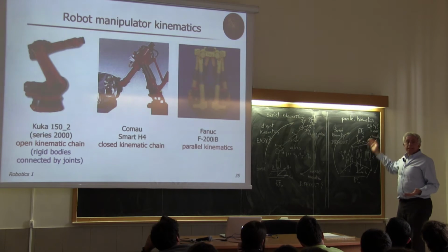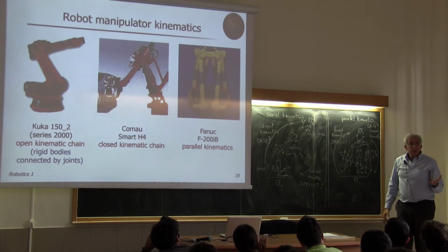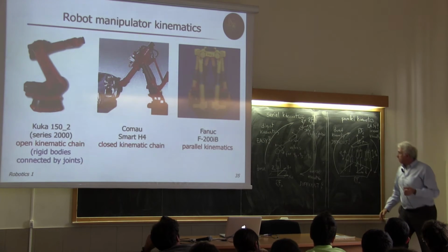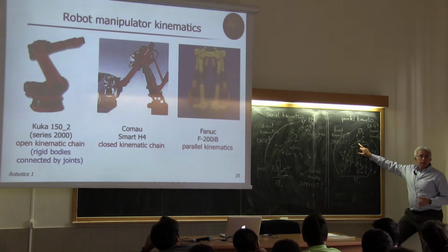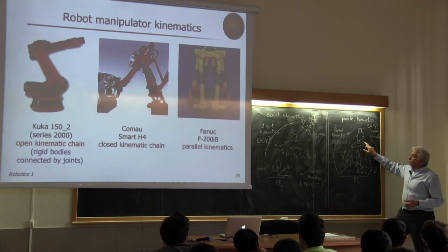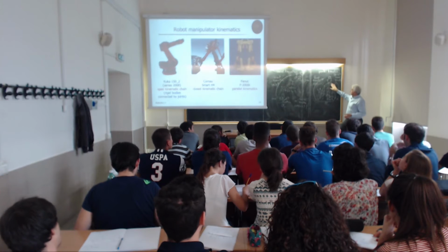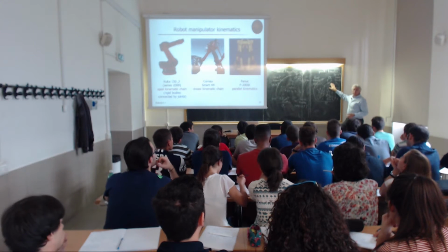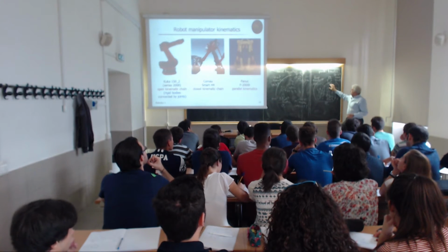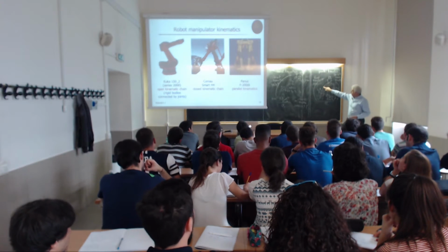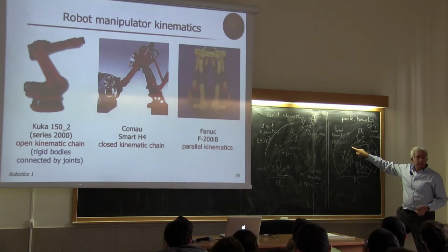And in fact, that is insofar as the inverse kinematic is easy. And you may convince yourself with a bit of intuition in this simple case, because if I'm assigning the position of this frame and its orientation, since this frame is attached to the top plate, then I can also characterize this anchoring point for this pair of legs.